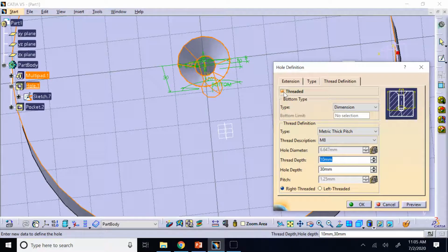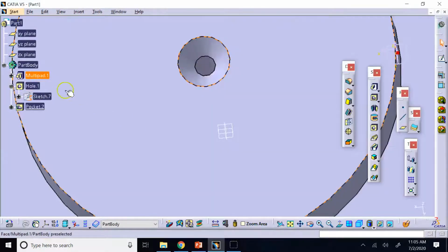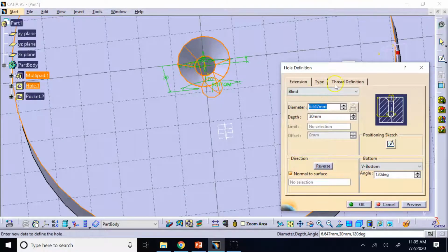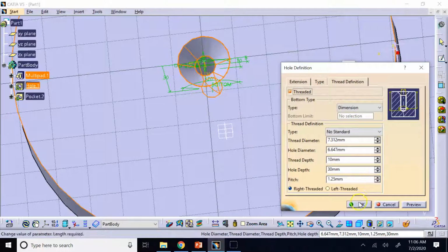Now look, if I turn it off, you see that 3/4 circle is gone. So whenever you see around the center hole in a hole symbol, there is this small black 3/4 circle around it, that means the hole is threaded. That's one way to basically find out if it's threaded or not.